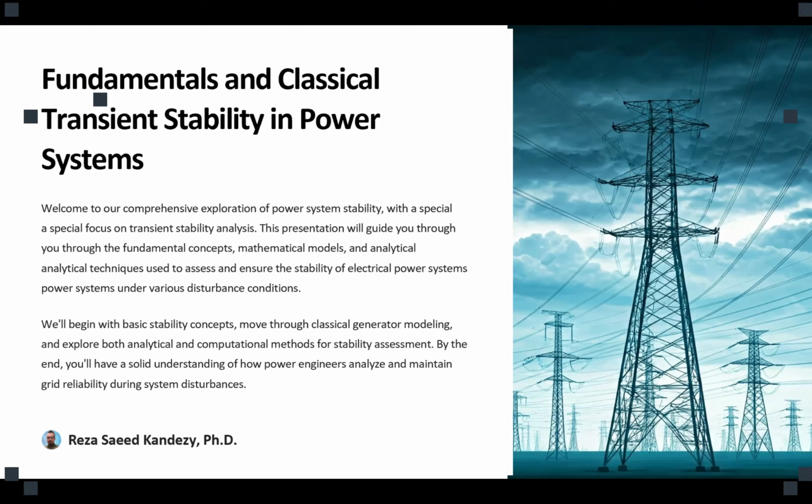And on Thursday, we talked about the effect of IBRs on those general methods and equations, and how we could modify the Jacobian matrix into a suitable power flow analysis for power systems dominated by inverter-based resources.